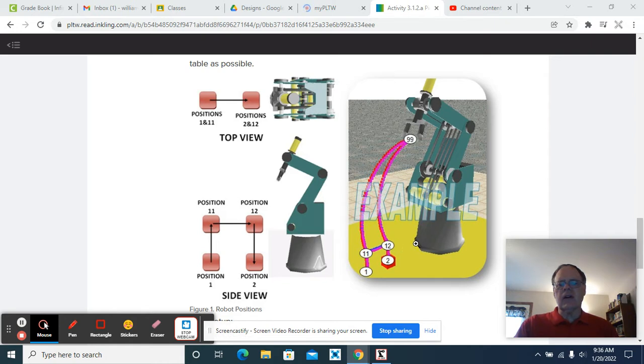And this is the idea behind robotics, movement of robotic arms. You always try to approach an object from directly overhead. That way you avoid hitting any other instruments or obstructions on either side of the object. So we always program a point directly above what we're going to pick up and place, just to make a smoother, safer move of the robot.